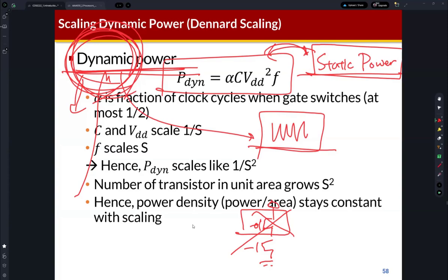If the circuit is disconnected, then the power is not consumed, right? Because the power is the current multiplied by voltage, and if the circuit is disconnected, there's no current, so power is 0. So in a CMOS circuit, composed of the PMOS and NMOS transistors, one of the transistors is off.